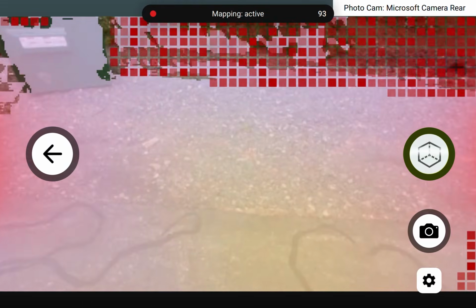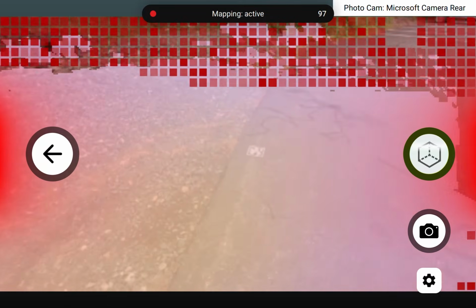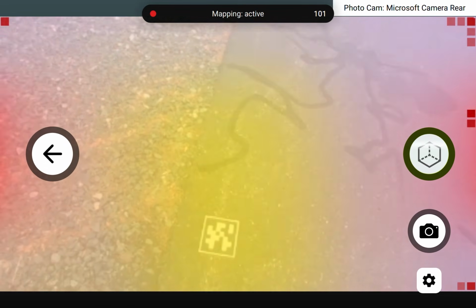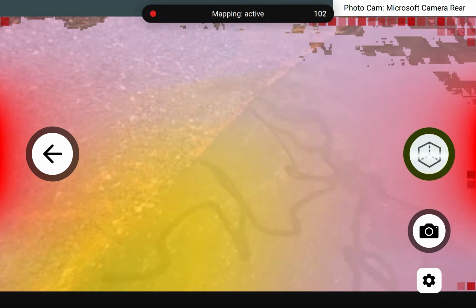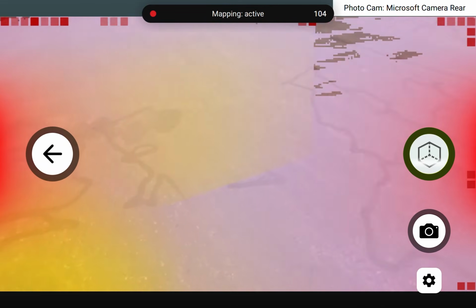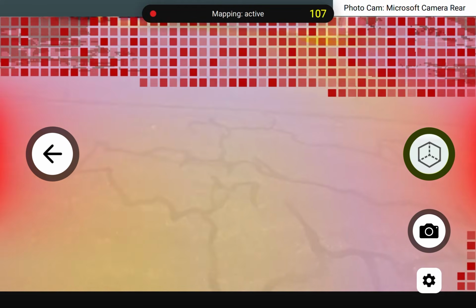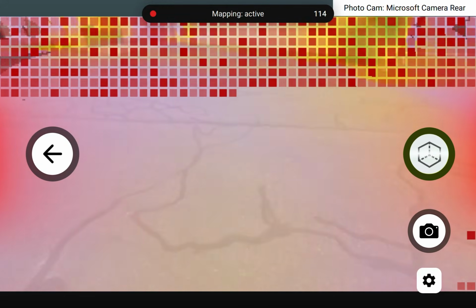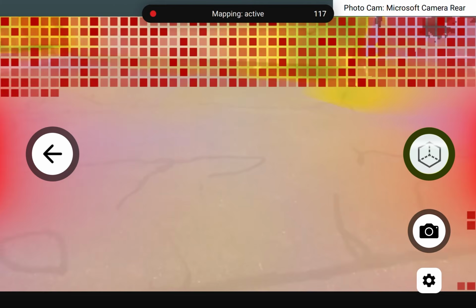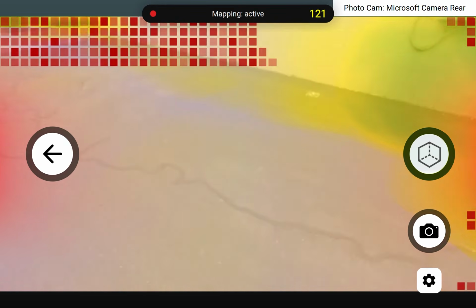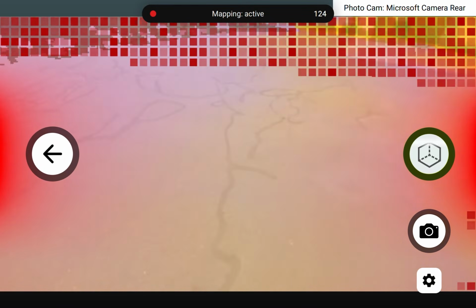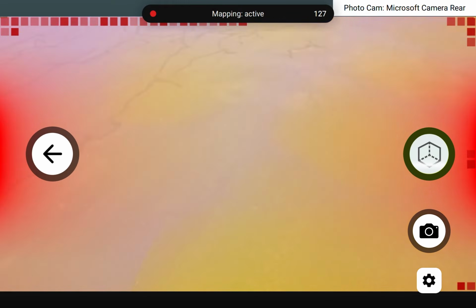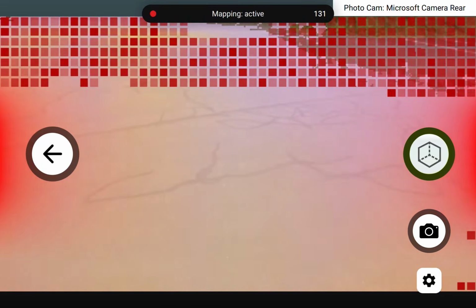So now we're going to just continue moving throughout our scene and filling in all of the different areas of interest. It almost feels like spray painting as we can visualize what areas we have and have not captured and how well. You'll notice that I also have a few more April tags scattered evenly throughout my scene and placed on the ground as a general best practice for additional loop closure automatic improvement, but also to add the ability to reference survey control coordinates to each of those tags before optimization for added georeferencing and accuracy improvement based on survey control. That is the second function of these April tags.